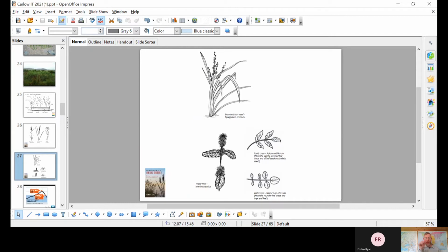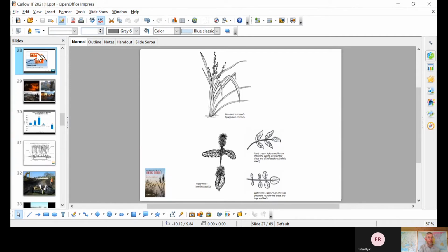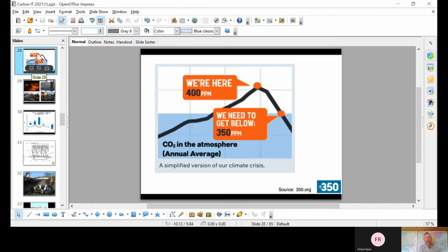And then if you want a little bit of variety for establishment phase, watermint is very good, fool's cress, watercress. Those are all very good plants for getting a good flush of material nice and early on in a soil-based constructed wetland. So that's the wetlands covered in a nutshell. I want to talk very briefly then about other systems that are very much related, but slightly different.